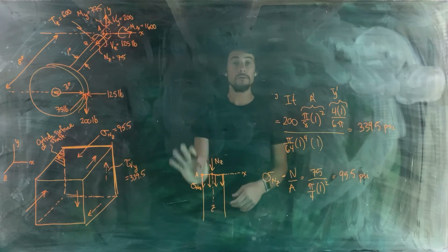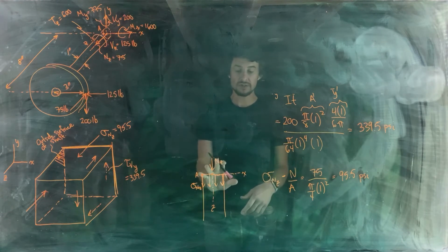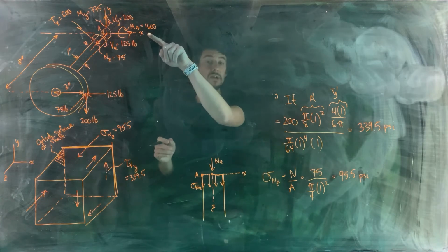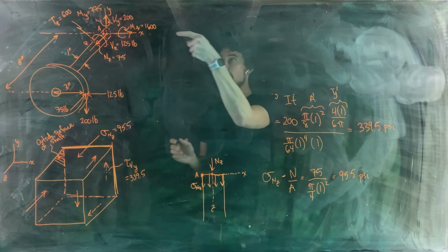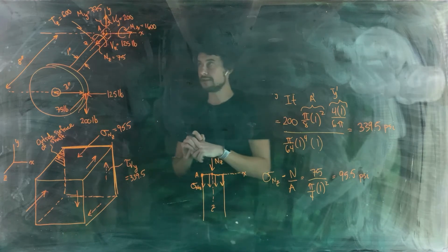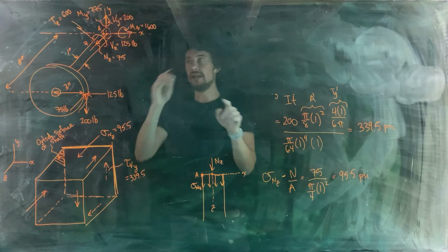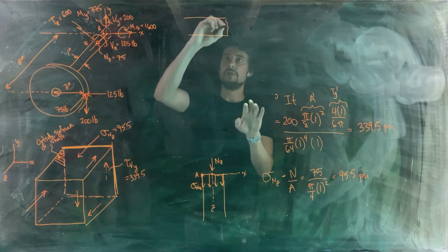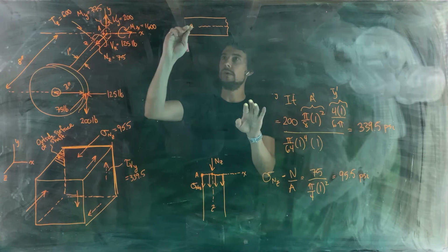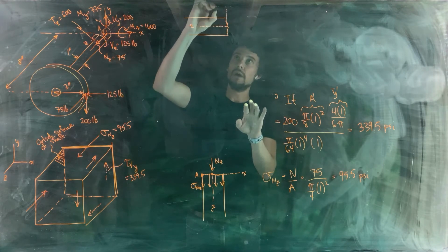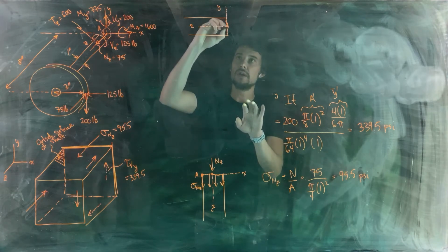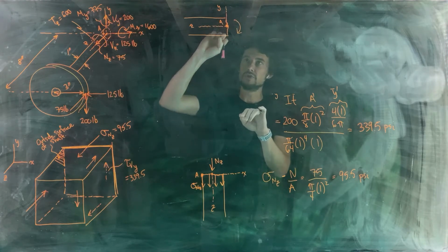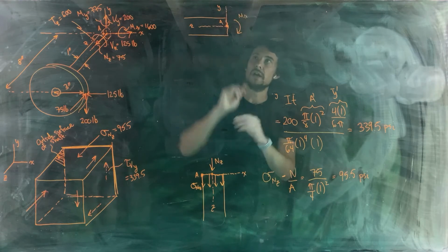For moments, if you find it helpful to do these little two-dimensional sketches to see the direction of the stress that's created at your point of interest, which I think it is when you're starting off, then for your moments, the most helpful two-dimensional view to draw is looking down the axis that the moment is acting about. So we'll look at the object down the x-axis, and we'd see our cut section like this with our z-axis going back this way and our y-axis going upwards. And point A is located right in the center there, and Mx is occurring around the x-axis, which is pointing out of the plane of the glass in this direction, Mx.